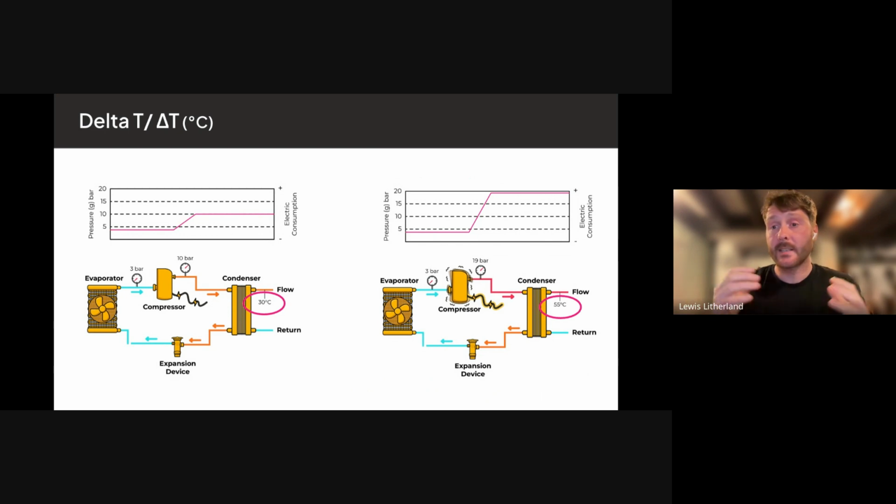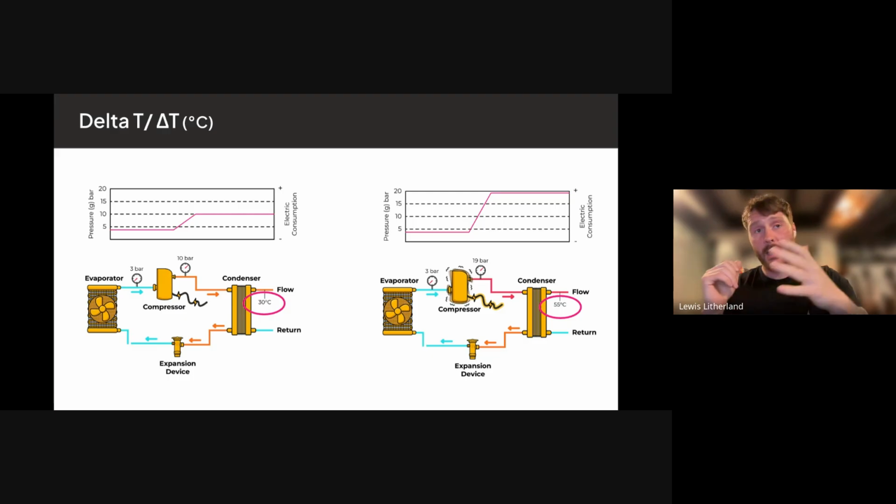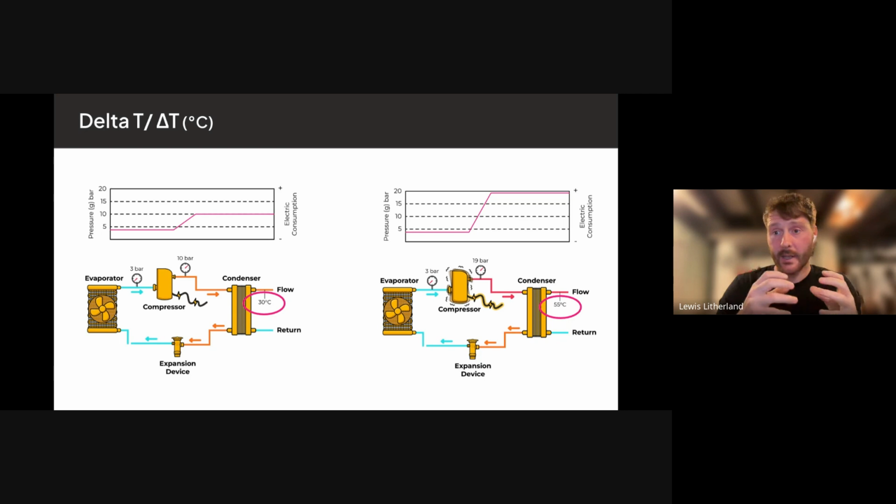For the heat pump, this is why you want to keep a narrow delta T. The one on the left, I'm also emphasizing the flow temperatures here. We won't go into how the heat pump works; you probably learned that in Enlightenment. But basically, the one on the left has a low flow temperature, which also means a low return temperature. So the difference in temperature isn't very high. When that water comes in, it doesn't need to be raised by a crazy amount. That has a massive benefit on the main part of this whole system, which is the compressor. That's the only bit that is going to cost the customer money. The more energy that uses, the less efficient it's going to be.